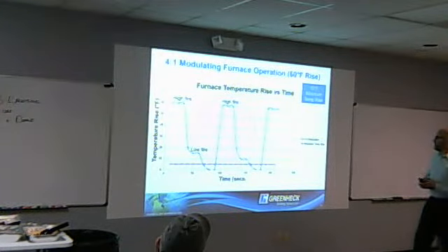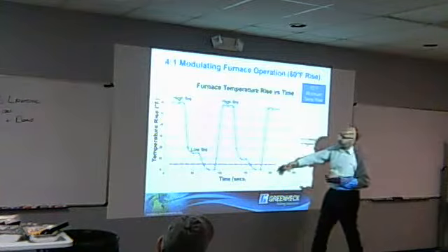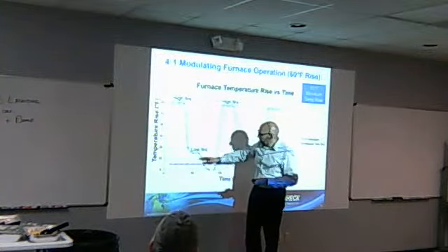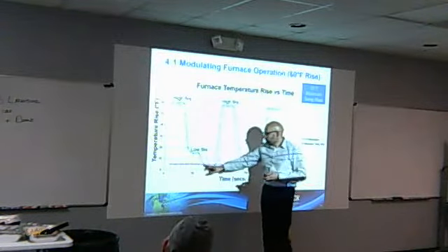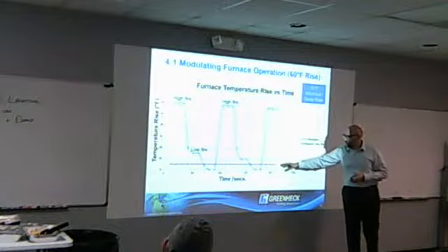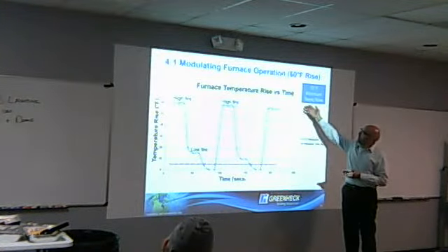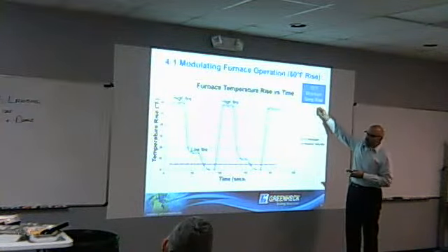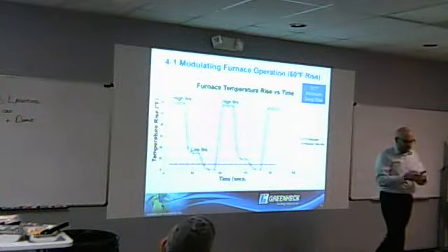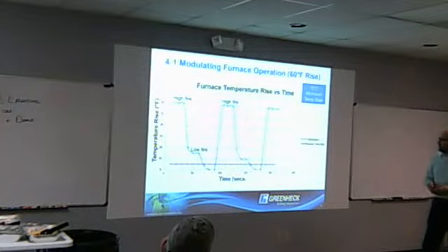You got it. So 4-to-1 modulation, high fire. About 50 seconds, it's going to high fire, then it's going to go down to low, and then it's going to say, okay, we're satisfied, if this was what we're trying to get to in terms of the required temperature rise. Here it's a low temperature rise, but we have a high 15-degree minimum temperature rise. So you see what happens, and people tend to feel warm, cold, and it's not always pleasant.